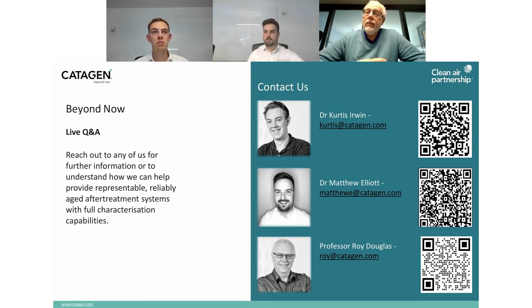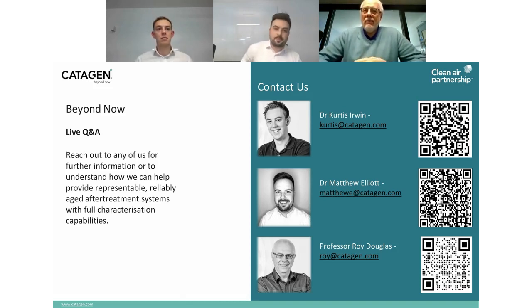Yeah, well then, just going on to that catalyst kinetic model, we've already used it quite a few times as backup for ourselves and to help understanding whenever we're doing an aging profile, that we can take the light off data and then feed it into the model to see, are we close to what we're expecting the final tailpipe emissions to be.